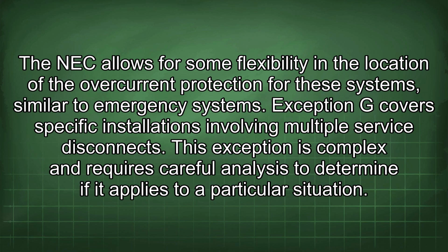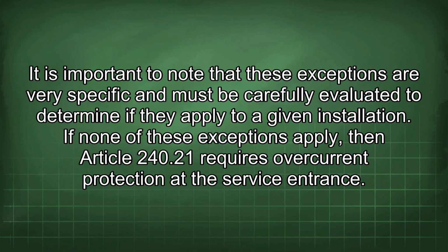This exception is complex and requires careful analysis to determine if it applies to a particular situation. It is important to note that these exceptions are very specific and must be carefully evaluated to determine if they apply to a given installation. If none of these exceptions apply, then Article 240.21 requires overcurrent protection at the service entrance.